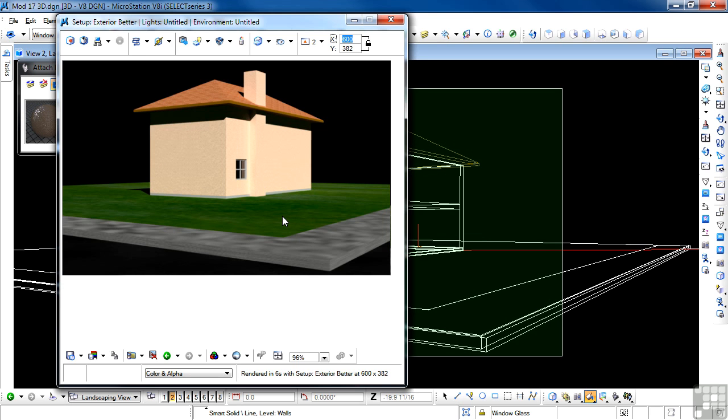Now, the reason I had you use this particular grass material was that at this distance, in terms of our viewpoint, you really can't see the blades of grass that specifically. And if you tried to do that, you would have a much longer rendering time. Plus, you're going to start getting patterns showing up from the material graphics files, which you don't want. So at far distances, a generalized pattern is better than a more specific pattern.